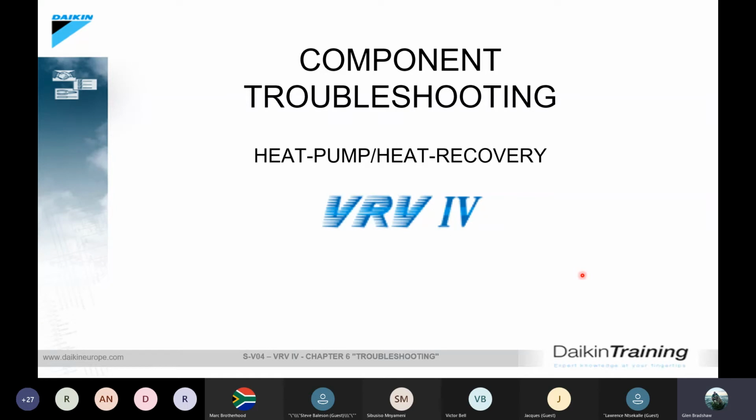I've come across a number of guys that, and I know that money's tight, but the guys will buy a multimeter from Midas, and when we use them on site, we find that they give varying results over a number of tests compared to something that is of better quality. Also, the wires inside the testing leads tend to be harder and they tend to break, and then the guys start getting all sorts of crazy readings. Now remember that when you're measuring something for electrical work, you actually put your life on the results that it gives you.